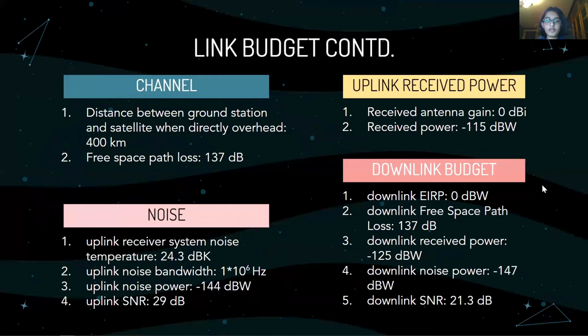Here's some more of our calculations. We found a free space path loss of 137 decibels, an uplink SNR of 29 decibels, and a downlink SNR, or signal-to-noise ratio, of 21.3 decibels.